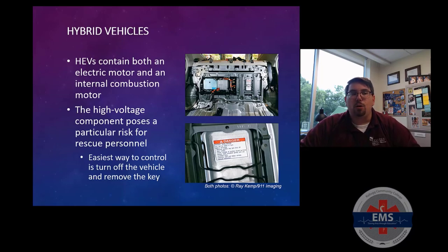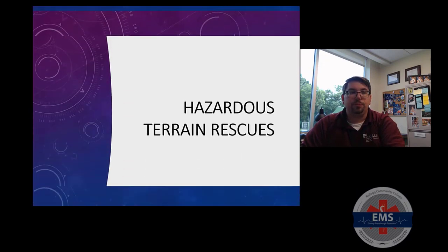It's very important that you take control, turn off the vehicle and remove the key, and be aware of the specific requirements for electric and hybrid electric vehicles when you're dealing with an extrication. Again, use those who are experts to help you navigate this. There are also a number of apps that you can utilize that will let you know, for extrication procedures, the safest way to disengage the battery or the power source for that vehicle.